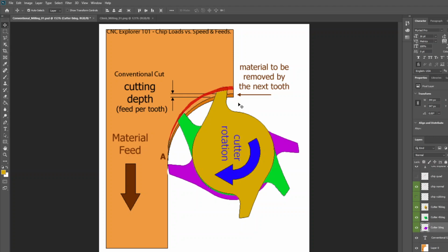We are putting a minimum amount of stress on the cutter, and we're also making a clean cut, and the chips are being pushed out as the cutters exit the material, and they carry heat from the cutting operation. So you always want to make sure that you're ejecting chips, and you want them to be not powder, but real chips of the width that you're trying to get.